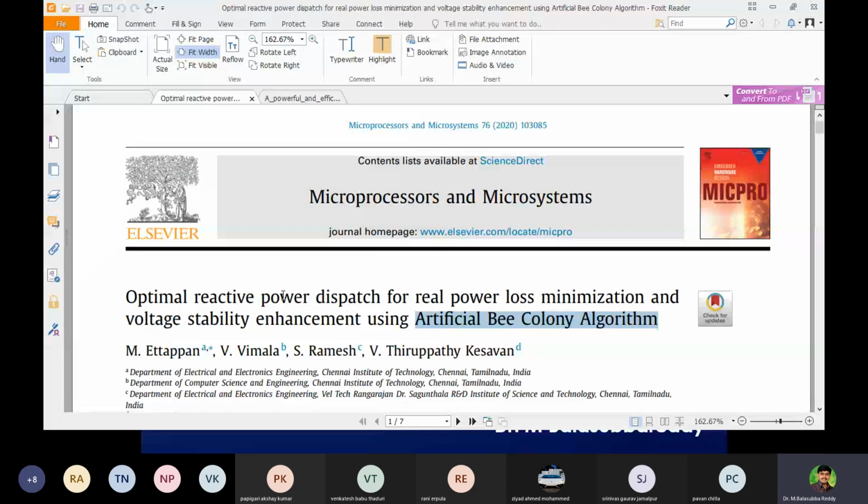Like in a 5 bus system, there is line 1, line 2 and so on. You can find each line flow, and you add all the line flows, S_ik plus S_ki, summed in the particular instance. That will give the total loss of the system. So that is one of the aspects, if you consider it as a loss.